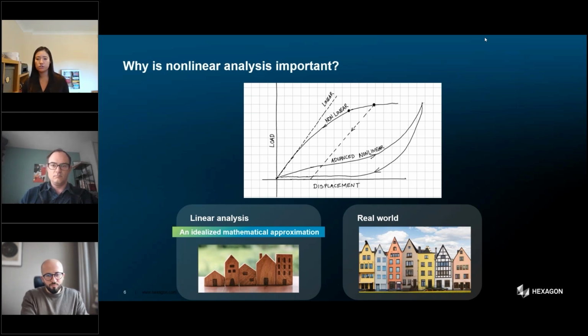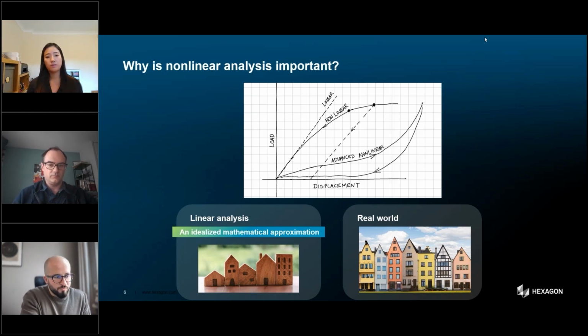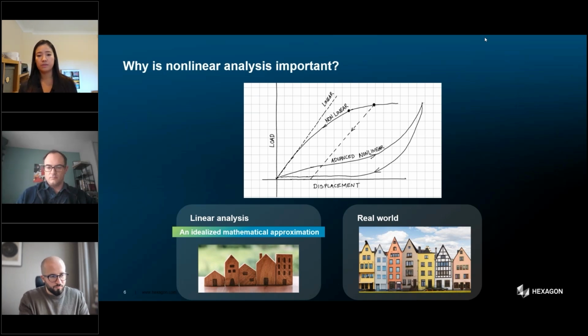These models are highly used because they're scalable. But when we look at the real world, as we mentioned before, it is not so neat. It is not linear elastic. We encounter nonlinear materials and behavior. Materials stretch and they yield. Some are time dependent and they exhibit creep and relaxation behavior. Materials could fail. Components can undergo large deformations. They might buckle, and some products rely on the post-buckling behavior to work. For example, snap-through mechanisms.